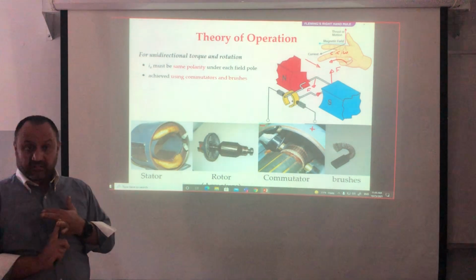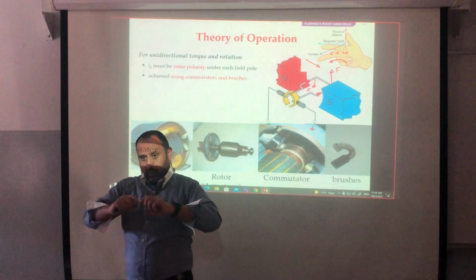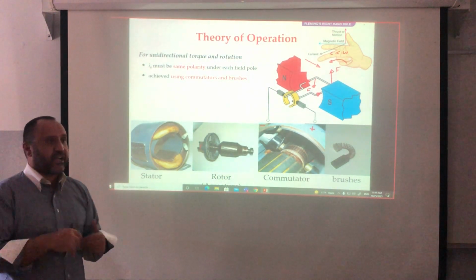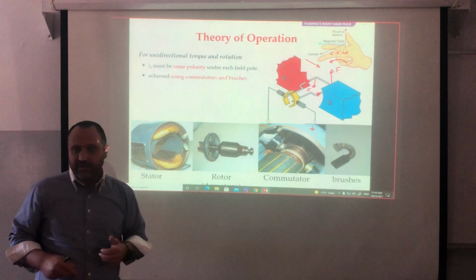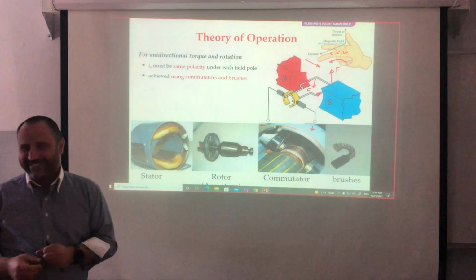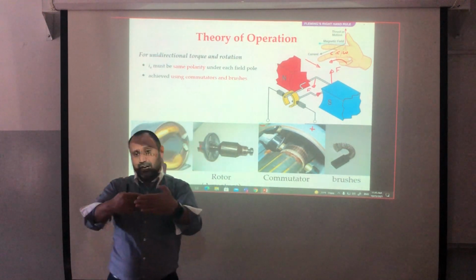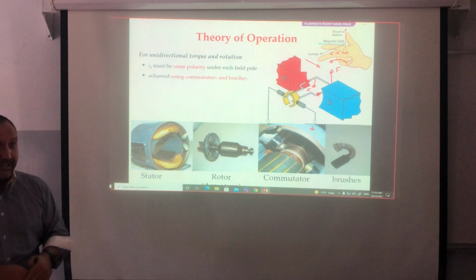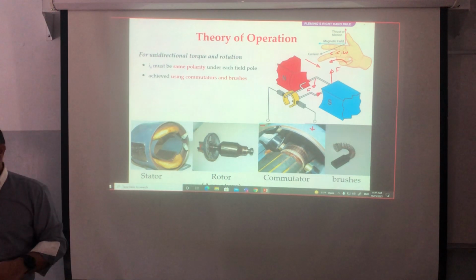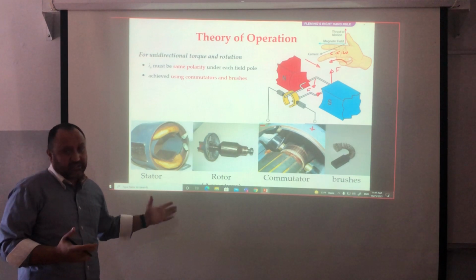It needs maintenance. Why? Because those are carbon brushes. While moving the rotor, the brushes will be eaten, so with time I need to replace them. What else? All the time I'm doing a short circuit, by the way. Why? While the commutator is traveling, two segments are shorted together, so all the time you will see sparks. But why do we use this one? It's simple.